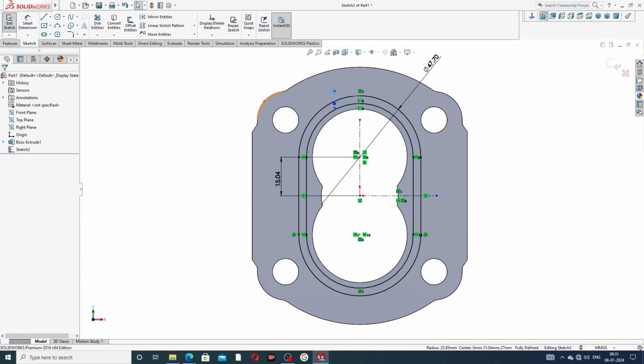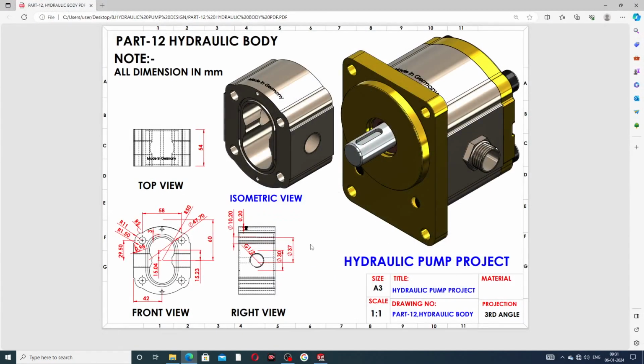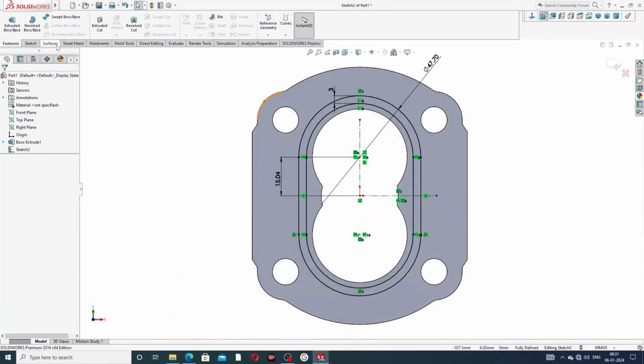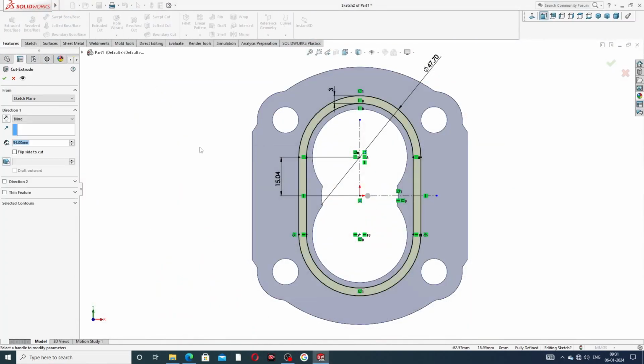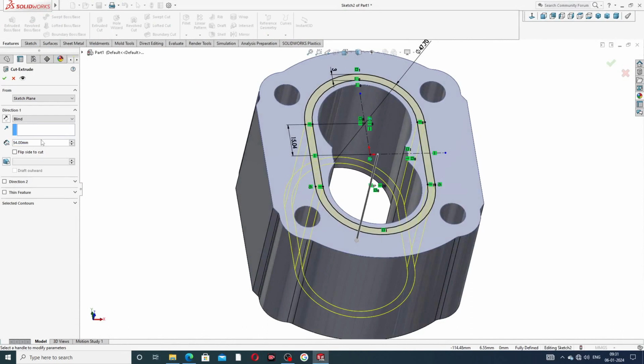and this offset is used here, and this cutout is only 2 millimeter, which is not mentioned here, but this is a 2 millimeter cut out, and use an extrude cut. Extrude cut is only 2 millimeter because this uses a rubber belt. 2 millimeter is perfect, and click OK,